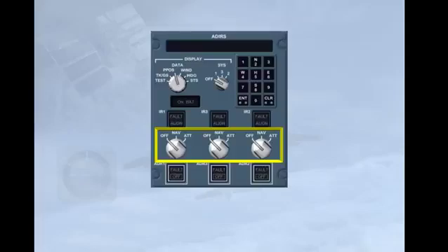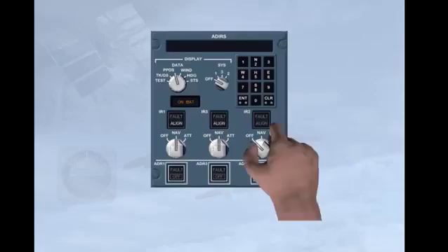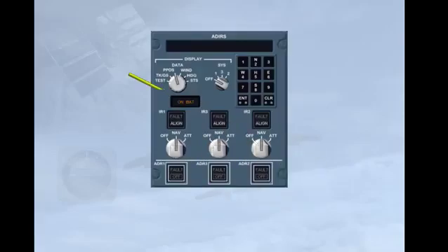In the navigation position, the ADIRUs are energized. The navigation position is the normal mode of operation, and full inertial data is provided to the aircraft systems. The on-bat light illuminates to inform the crew that the ADIRU system is being powered by aircraft batteries only. The light also illuminates for a few seconds at the beginning of a full alignment as a test of the battery circuit. We will discuss this further in the normal and abnormal operation modules.